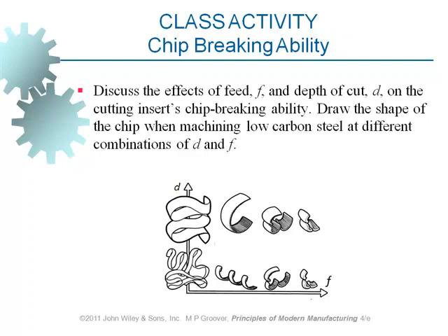Anybody who has got similar sketches? No? What's the question of yours? No question? Okay. Of course, when F is low, it is quite possible that we do achieve a continuous chip like this one, and the depth of cut D decides the thickness of the chip which is being produced. And when F is really high, what we get will be discrete pieces of chip.